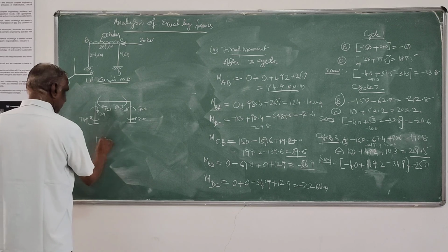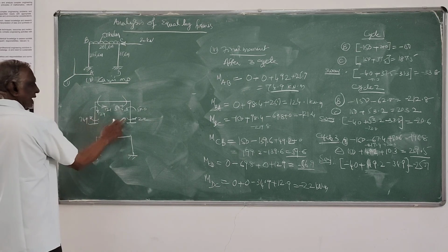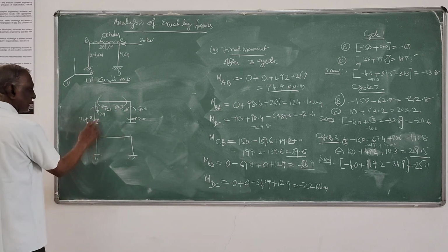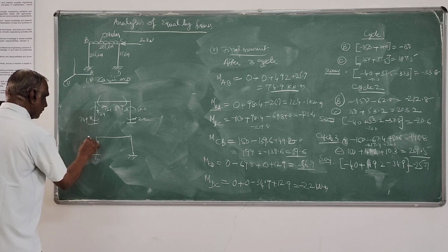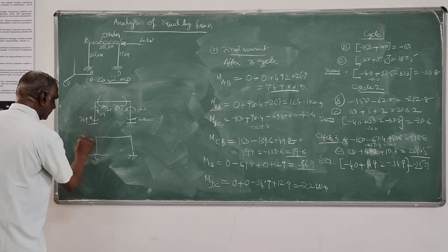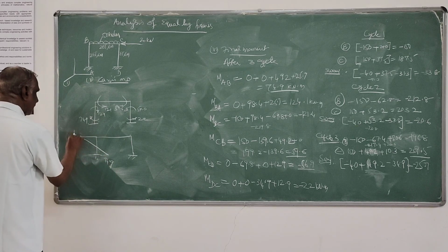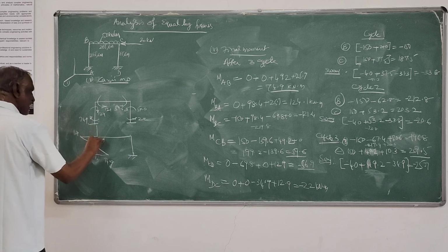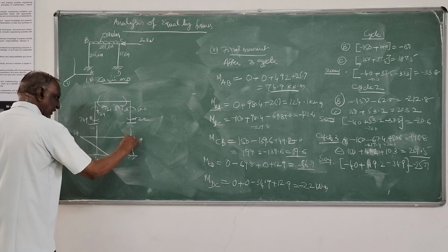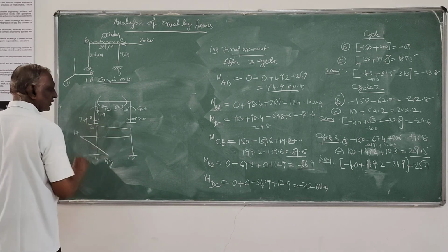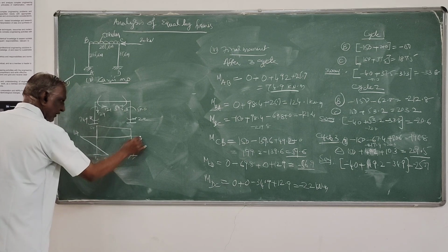And you can plot. First you plot this fixed end moment on the tension side, that is on the tight side of this arrow, that is 74.9. Here it is 124, like this. This is 74.9, 124. Here also it has to be 124. That slight error is there. And here 59.6, so that you can take it. Here also 59.6. Here you got 22.